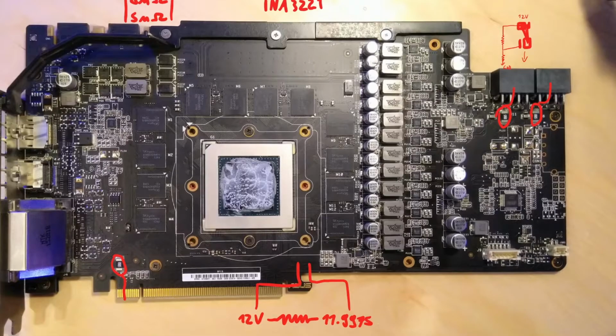So one way to get around this that doesn't involve BIOS flashing, because, well, earlier models up to the 900 series, you were able to just make a custom BIOS. You just took the BIOS from a card, plugged it into a BIOS editor, and then you could just take the power limit and set it to whatever you want. Beginning with the 10 series, NVIDIA started to encrypt their BIOSes, so you can't make custom ones anymore, so the thing you were left with is just find a card that has a better power limit and try to flash that BIOS. But that didn't always work, especially for extreme overclockers.